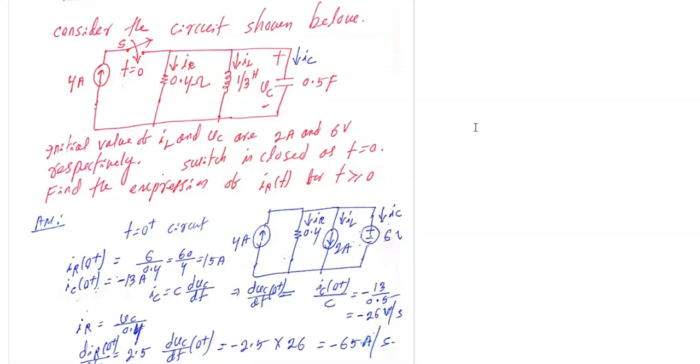Before all this procedure, you need to find the initial conditions, like the initial condition of one variable, and then its first derivative is required for finding the arbitrary constants. Then we'll use the forced response, or you can say the particular integral. Then we'll add them together, then find the arbitrary constants to get the result. Pay attention to this exemplified question.